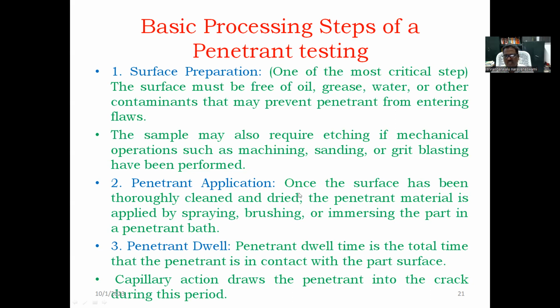Penetrant application: once the surface has been thoroughly cleaned and dried, the penetrant material is applied by spraying, brushing, or immersing the part in the penetrant bath. Penetrant dwell time is the total time that the penetrant is in contact with the part surface. Capillary action draws the penetrant into the crack during this period. Dwell time may be 10 seconds minimum.